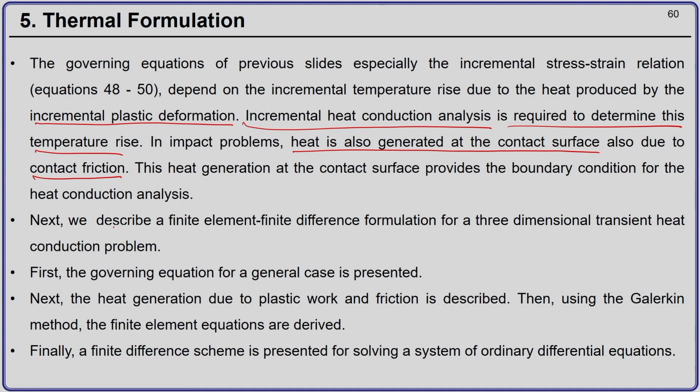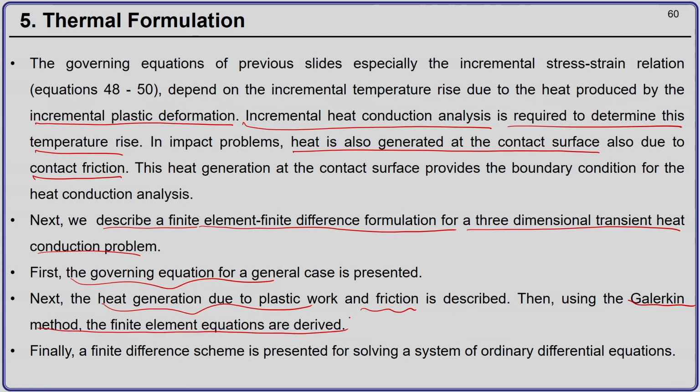So, in this section, we describe a finite element, finite difference formulation for a 3-dimensional transient heat conduction problem. First we will present the governing equation, followed by expression for the heat generation due to plastic work and frictional heat, and then we will use the Galerkin method for finite element discretization, and then we use the finite difference scheme for solving a system of ordinary differential equations which is of first order.